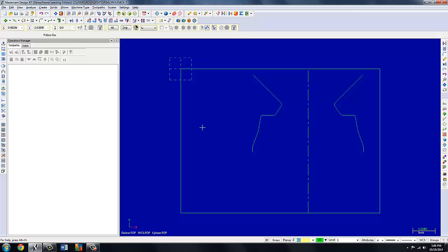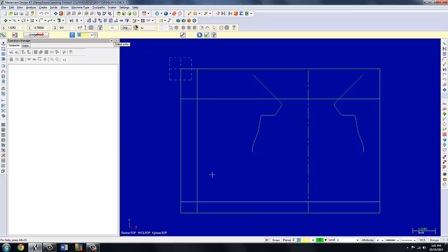The first part of the handle geometry I'd like to create is the plateau as well. It's always the low-hanging fruit. So I need parallel line. The dimension from the print is 1.35. Select a line, indicate direction, and there's my handle plateau. I've also got an intersection down at the lower left-hand corner I can use for different geometric elements. So I'm going to stay in the parallel command and pick an offset direction of 0.75. Pick a line and a direction, except that one. I've also got an offset direction of 6 from the top. So I'll pick a line and a direction there, and this gives me an intersection point that I'll be using later. Check out of that.